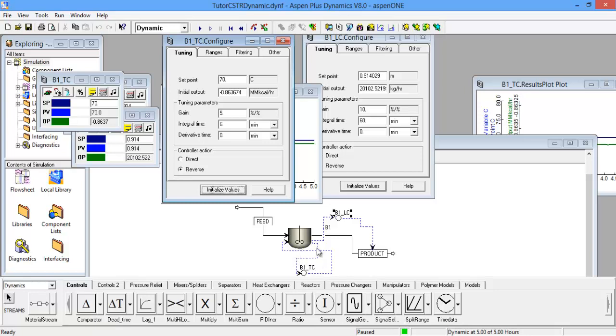The input to this temperature controller, if it is high, that is the temperature is higher, then the output is that we should reduce the energy that this one is generating, by increasing the flow rate of the cold stream. Okay, so with that, I hope we are able to get the difference between reverse acting and direct acting.